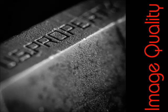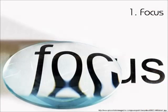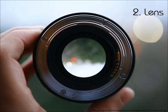So we need to let enough light into our camera, and those three things are the main controls we have for doing that. So what I want to think about now is what makes a good photo. We need high image quality if we're going to process it photogrammetrically. And there are 5 things I want to touch upon here. Firstly then, focus. We need our subject to be focused on the image plane of our camera, and that needs to be sharp. Typically what we would do with an SLR is to focus it at infinity, given the distance from our camera to our object.